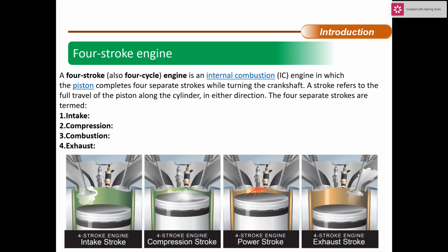Now, the four-stroke engine. A four-stroke engine, also called a four-cycle engine, is an internal combustion engine in which the piston completes four strokes while turning the crankshaft. A stroke refers to the full travel of the piston along the cylinder in either direction. The four separate strokes are termed intake stroke, compression stroke, combustion stroke, which we also call the power stroke, and exhaust stroke.